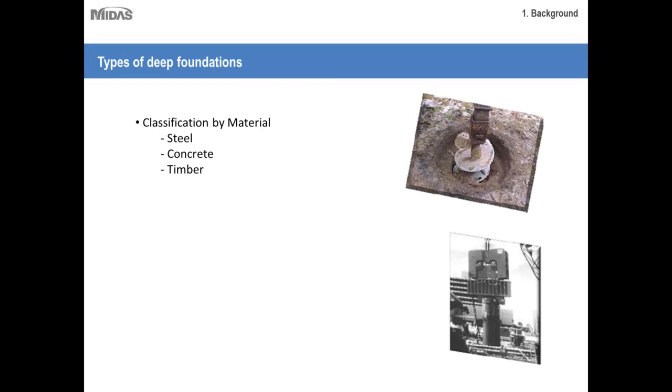And therefore, if you are using numerical analysis, you are able to estimate the true strength of the material, the true interaction between soil and structure, and the true behavior of the soil, therefore allowing you to fully optimize the strength of the material. In many cases it has been found that you could reduce the number of piles under a foundation if you are fully optimizing the strength of the concrete of the pile.